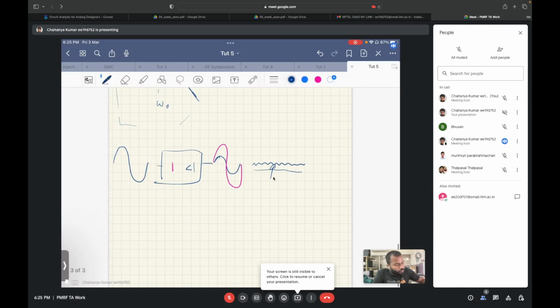So you don't want to put 0.707 quality factor first. You should always put the lowest quality factor first. That is 0.518 you will put at first. Then you will put 0.707. And at the end, you will put 1.932. So this is the correct order of placing the biquads: the higher the quality factor, the later you place it.